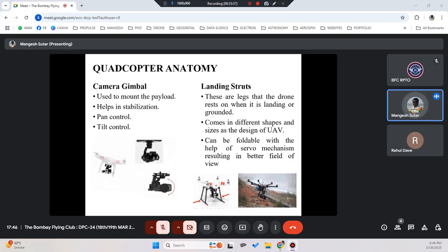So first, it is not depending on the camera motions, or motions of the drone, or position of the drone. Drone will be in very stable flight, in hovering condition, and using the gimbal, you can change the angle of the camera to capture the particular location. You can capture from 0 degree to 90 degree facing the ground itself. You can capture in any direction, and you can take a 360 degree shot also, by using pan and tilt motions. You can pan completely 360 degree to get the complete view of the area.